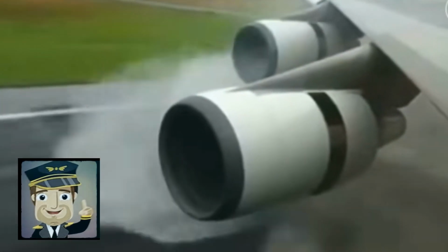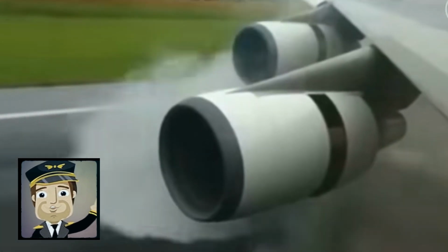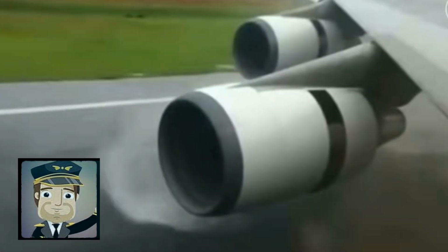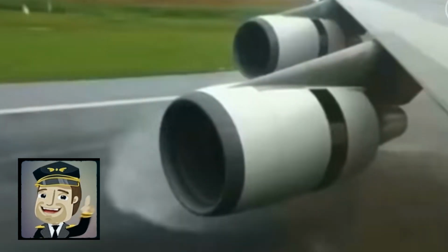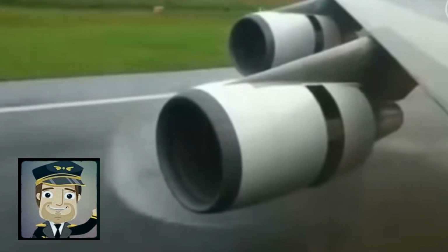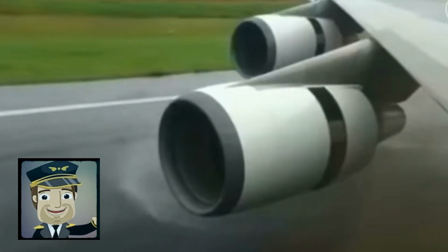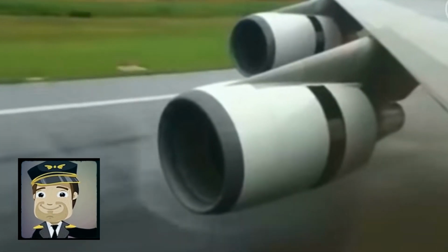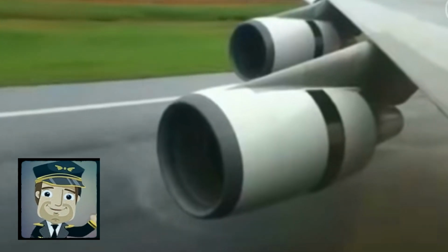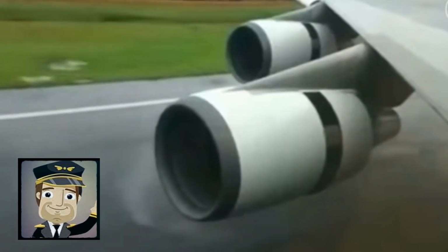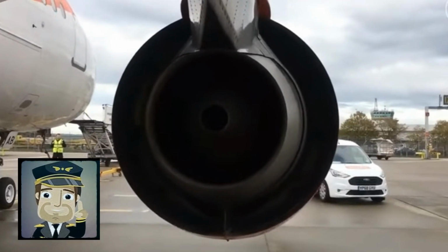There are three main types of thrust reversers used in commercial aviation: clamshell doors, bucket doors, and cascade-type fan reversers, the latter being the most common in modern turbofan engines. The bucket door type, often found in older turbojet engines, uses a set of metal doors hinged at the rear of the engine that close over the exhaust stream, redirecting gases forward and outward.